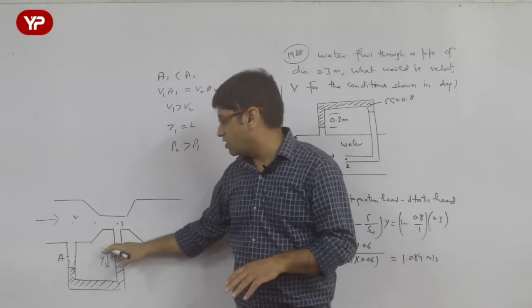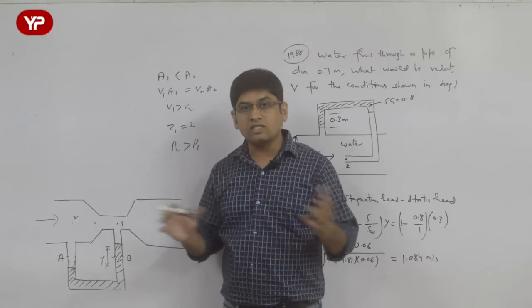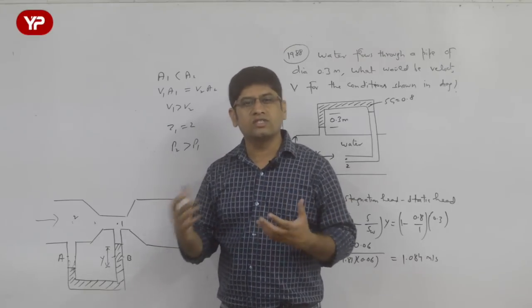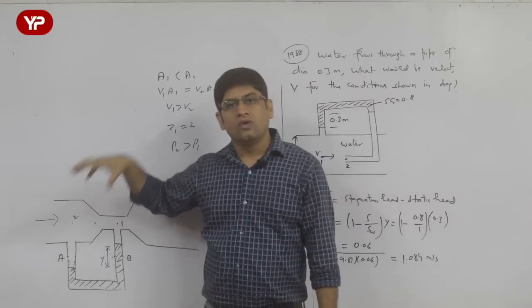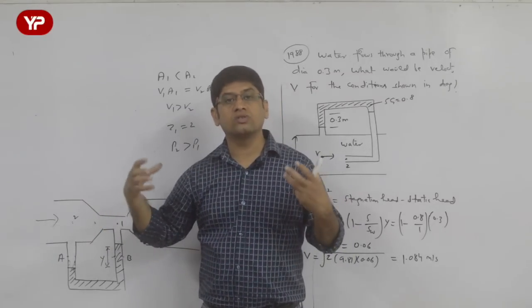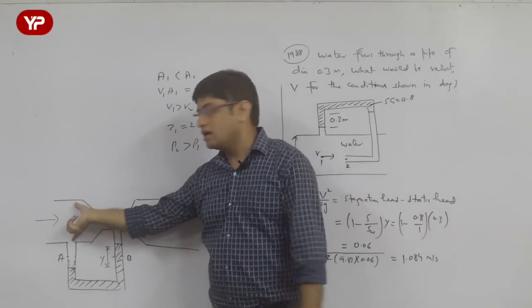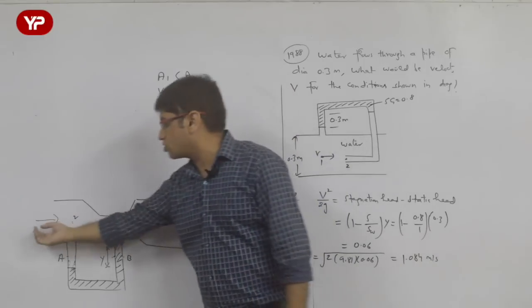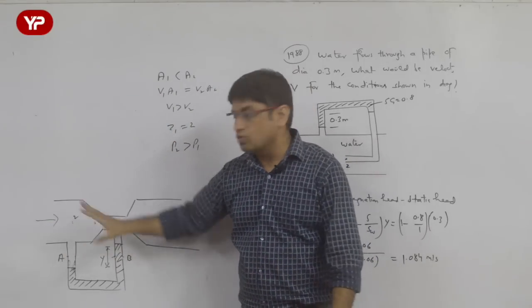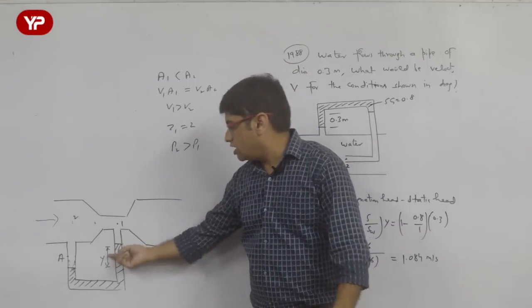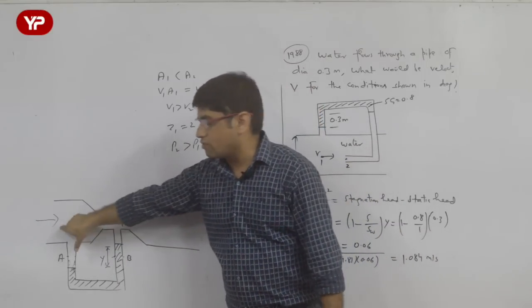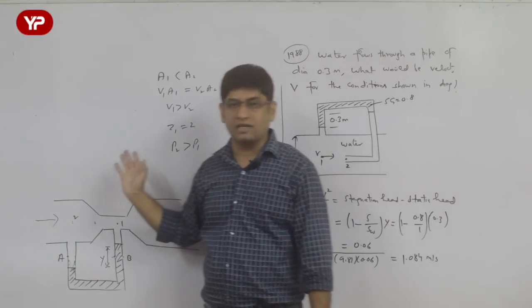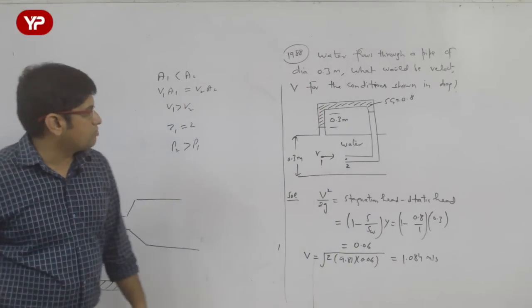Again the liquid level is going to rise, because direction of flow is related to friction loss, and we are not considering friction loss. We are considering the pressure difference because of area change. Area at section 2 is more, so pressure at section 2 is more. So mercury is only going to rise in B, whether the direction of flow is from this side or from that side. So remember this particular thing.